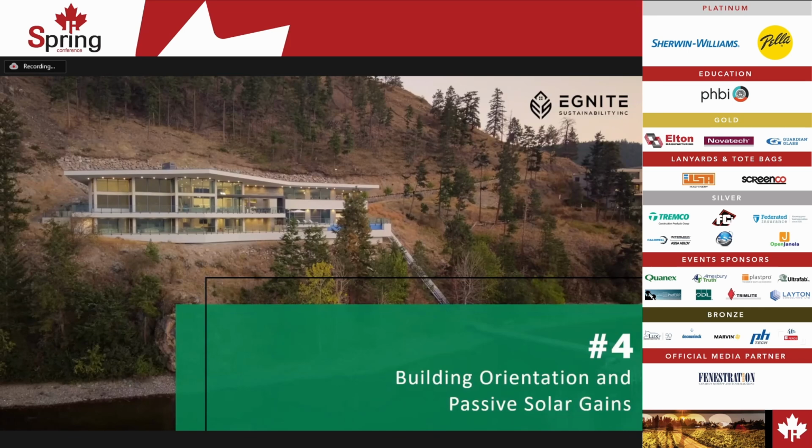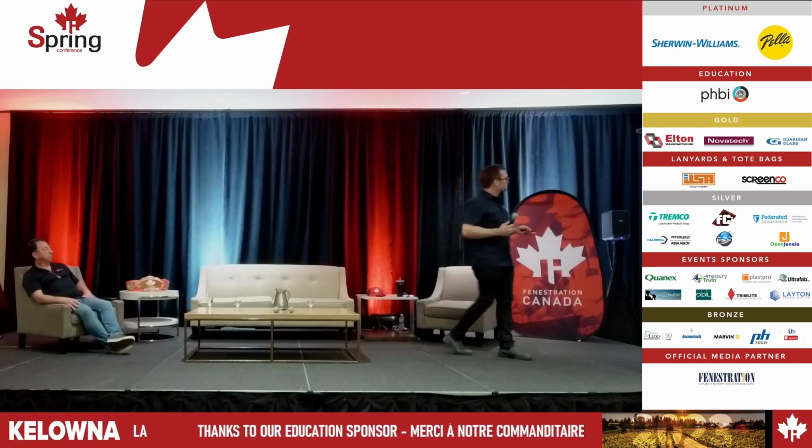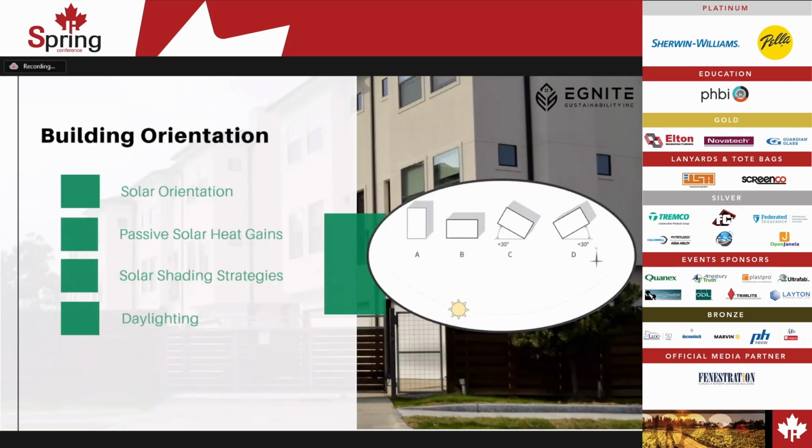Alrighty, I'm going to be moving into building orientation and passive solar gains. Just to recap, regarding some building science practices that we always look for when we're trying to achieve a high-performing Step 4 and Step 5 building: anytime we can orient the majority of the windows facing south, and we can capitalize on good overhangs, that's the way we build most cost-effectively to the upper level steps.